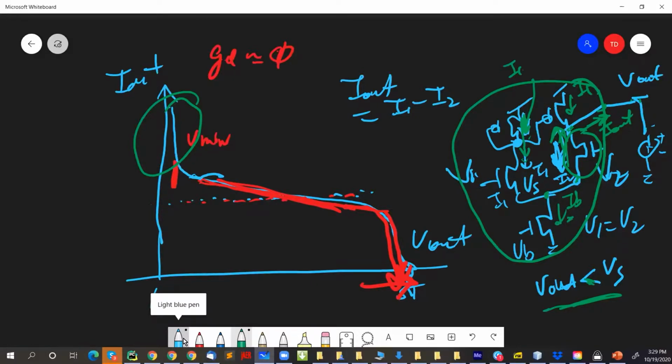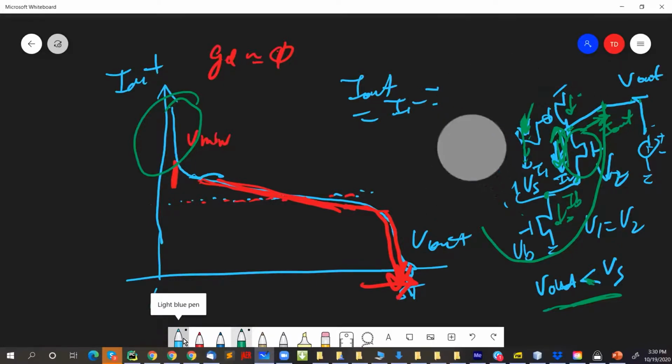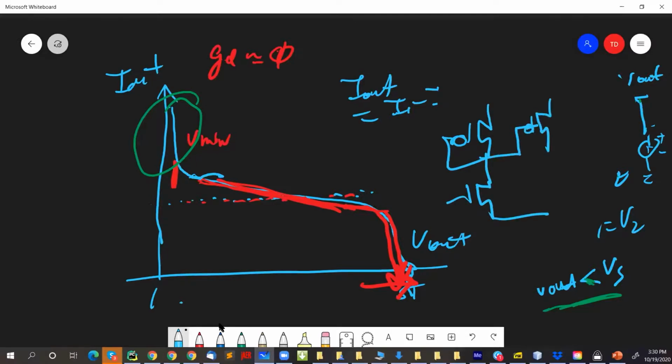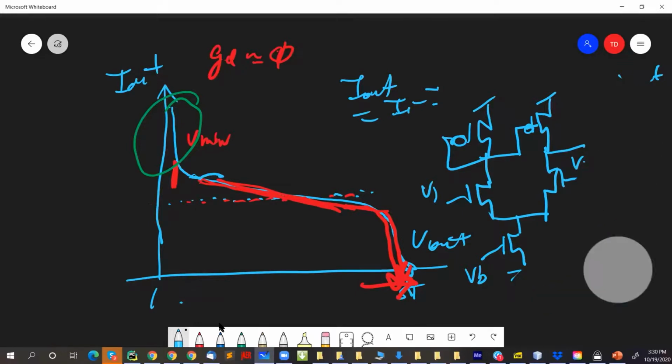And the same thing here, when you make V2 greater than V1, then I2 flows to here, but then the net current, okay, this is probably going to be ugly to see till I redraw everything. Just remember Kirchhoff's current law applies for steady state. So everything will move to where it needs to, so that the circuit voltages won't change anymore, but it wouldn't be the transfer function that you're hoping to get. The transfer function is something that you get only if all the transistors operate in saturation. So even if this transistor goes out of saturation, then you no longer get this nice transfer function anymore. You got it, Nicola?